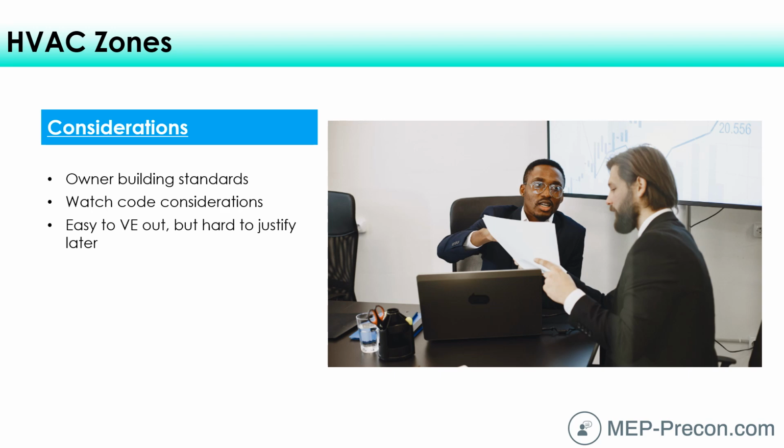If it's a VAV system, that's not too hard to retrofit, but any type of hydronic system, a fan coil system, either a 2-pipe or 4-pipe fan coil system, or a water source heat pump system, could be pretty costly just because it's not as easy to cut into water pipe as it is with an air pipe, like a VAV box system. So just qualify that in your proposal and discuss.